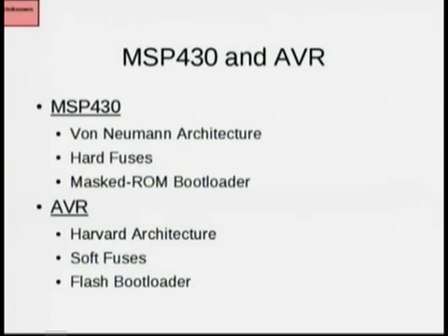For every guess of the password you make on these vulnerable chips, the password comparison takes 2 clock cycles longer. So you can run your password, measure the amount of time, and then if you send your traffic in the correct weird way, the difference between your beginning the broadcast and getting back a non-acknowledgement telling you that your password is wrong reveals the password.